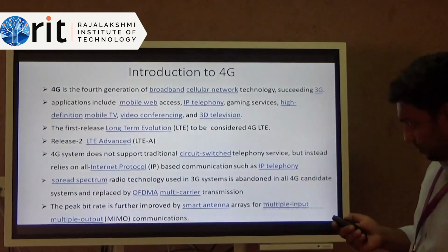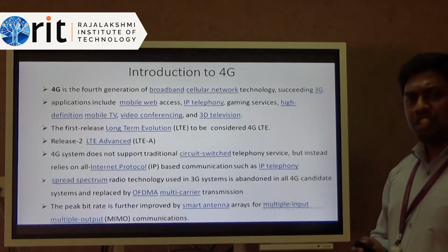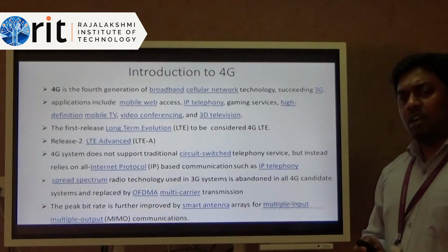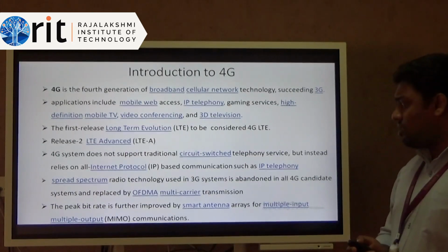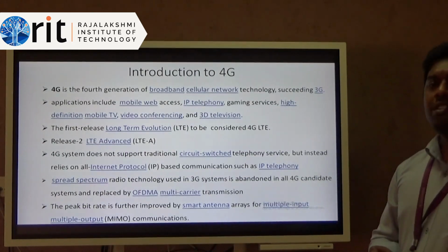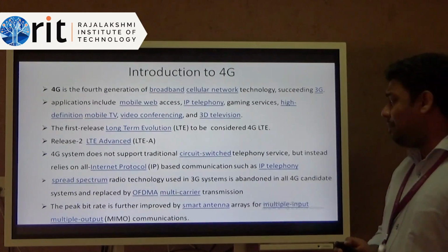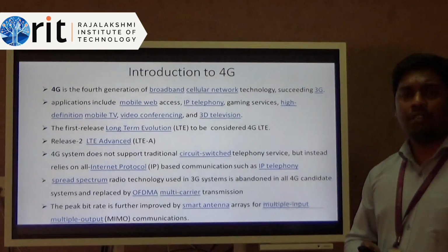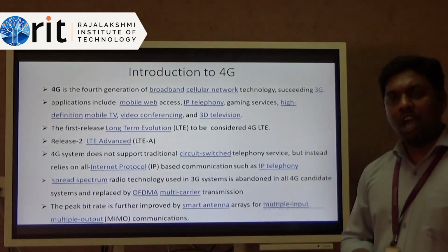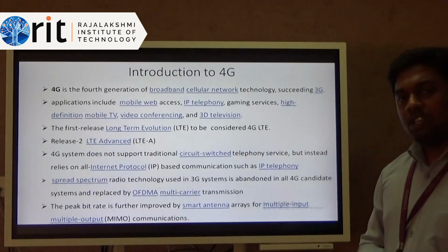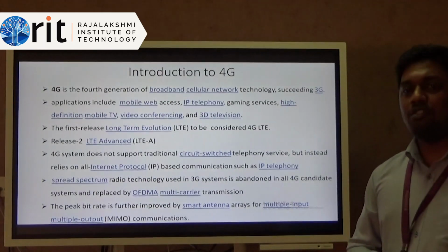Later on, let us look at the features added to 4G and the features removed from the earlier technologies like 3G and 2G. 4G does not support circuit switched services, but it supports internet protocol, that is IP-based communication. Why? In 2G, voice calls are transferred through what we call circuit switched services. 3G supports both circuit switched services, that means it carries a voice signal, as well as data services, that is packet-based services.